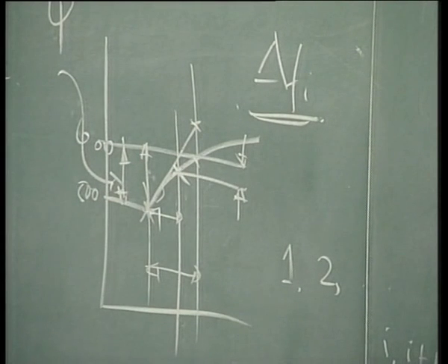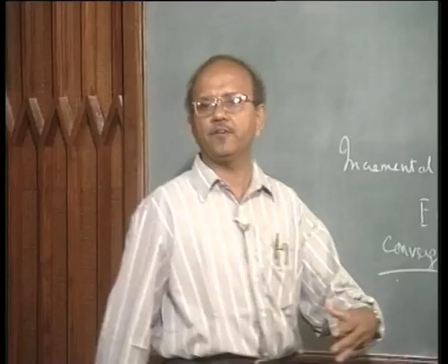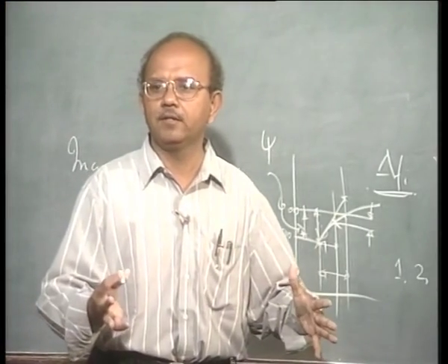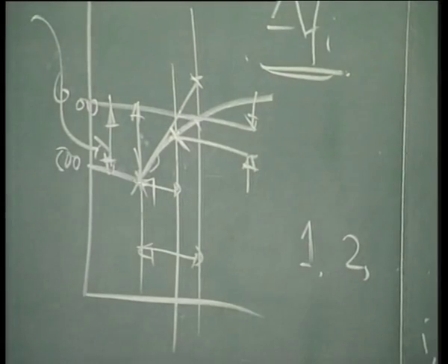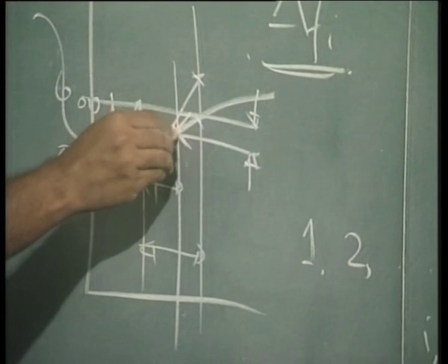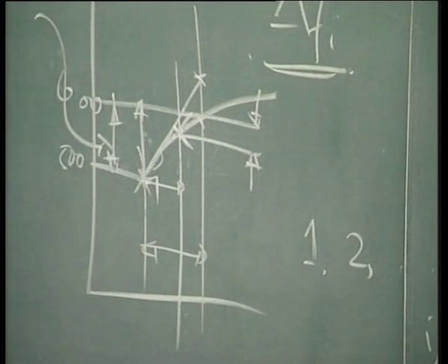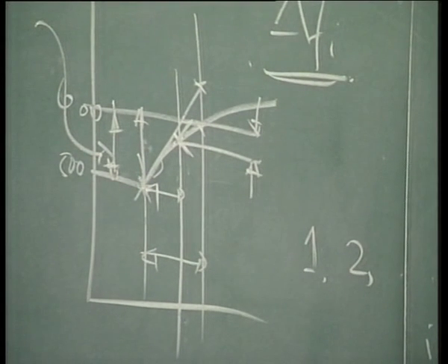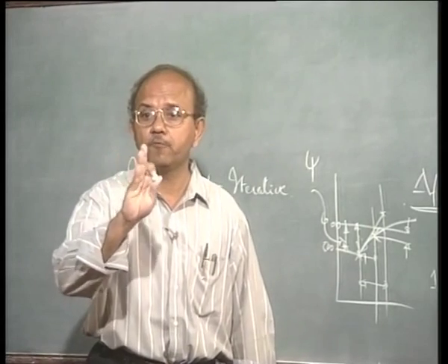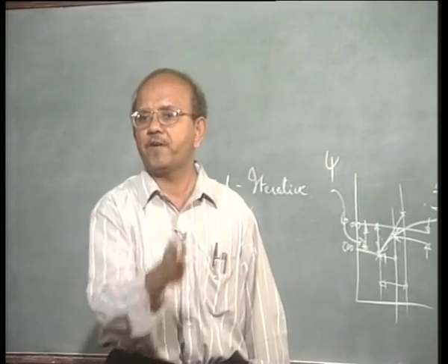I go to that point, I have new delta d, I calculate the stress, and find that the stress is not good enough to compensate for the external load. This is what I find. So I go now to the new point. What is the new point? The new point is this. So I again calculate there one more Et. Is it clear? So I am there after the first, this is called iteration. I am in the same increment from 5 to 6, but I am iterating between 5 and 6.